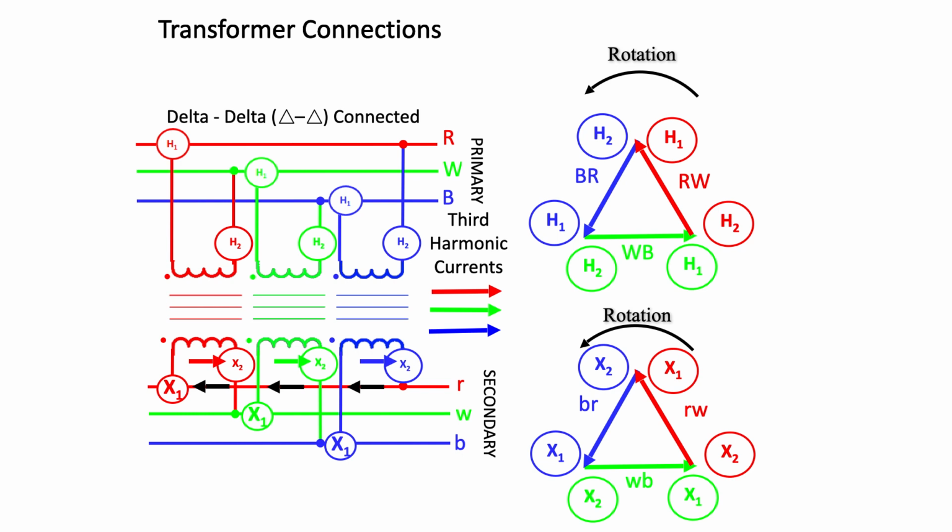The delta connection is used for transformation in a medium voltage range where a neutral point is not necessary for load purposes. Transformers with a delta-to-delta operation must have the entire winding and all the bushings insulated for the full line-to-line voltage of the circuit to which they are connected. Therefore, construction is more expensive.